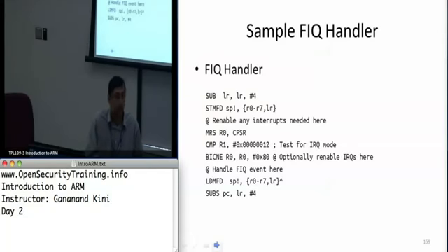And if you had IRQs and FIQs enabled when you came into this mode, it would restore that state back, as opposed to actually, once you re-enable it, all that's doing is it's allowing more interrupts to occur while just this FIQ handler is being run. And once you restore it back, right, you could save that back to the CPSR if you wanted to, but generally we want to return to a state that was as it was before we entered this FIQ handler. So.